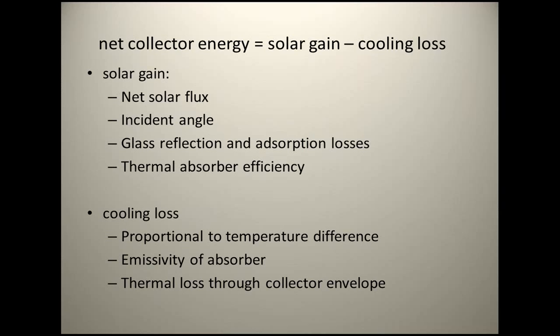And then there's the thermal absorber efficiency, and that's really been worked on. That's a high-tech part of this because they've had almost black body type collectors. The material properties of the collectors are really good. Like 97% of the energy that falls on the collector gets absorbed on these copper plates and transferred to the copper tubes. So that part's really done well.